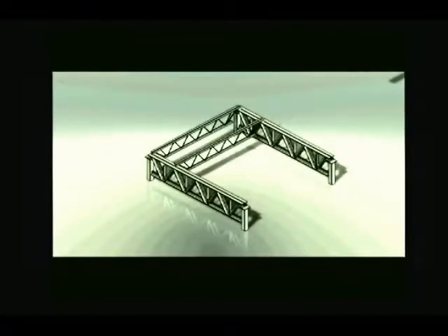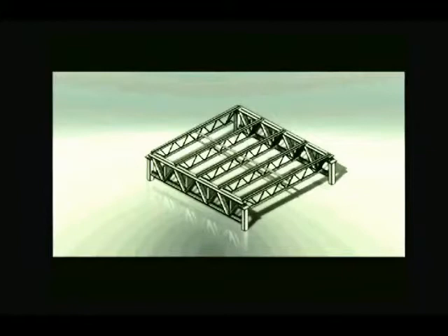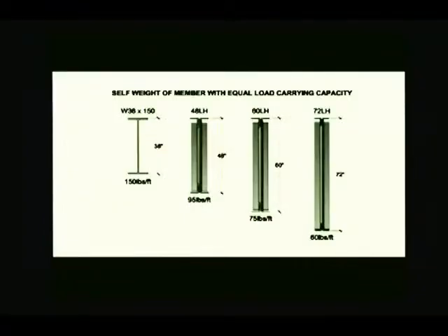Steel joist girders are primary structural members designed to support the concentrated loads applied by the steel joists. Like the joist, there are significant weight and cost advantages for joist girders when compared to solid web wide flange beams.